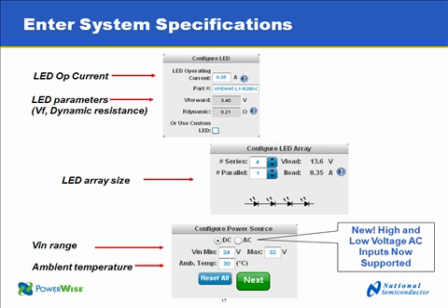Then you need to configure your LED array. So in this tool, you are responsible for saying, okay, well, I need to have 5 LEDs, and I want them in series or I want them in parallel. And I will show you later the new tool takes care of that for you. But here in the traditional tool, you are responsible for that, and you're given control over that.